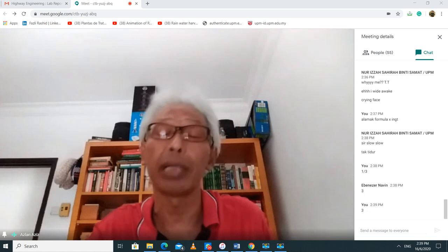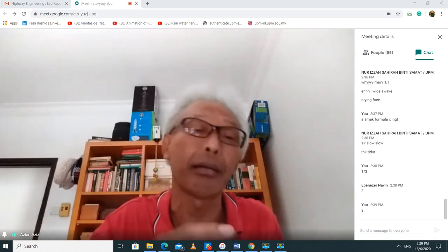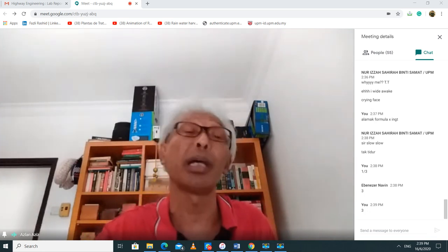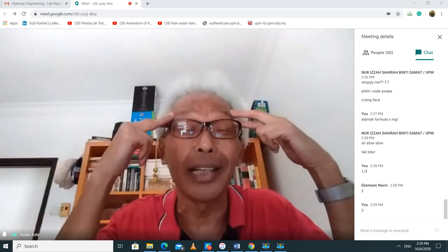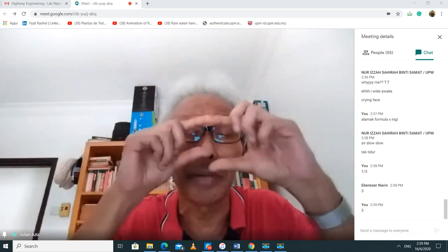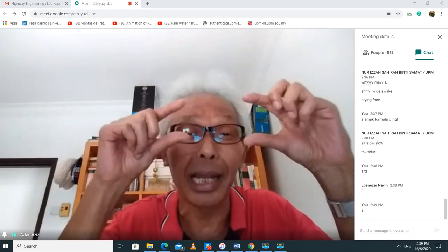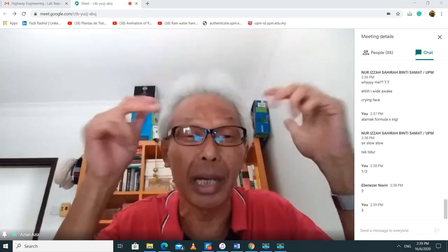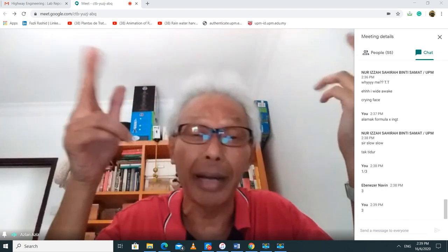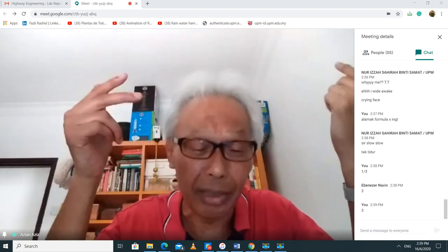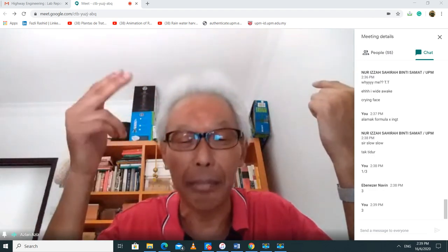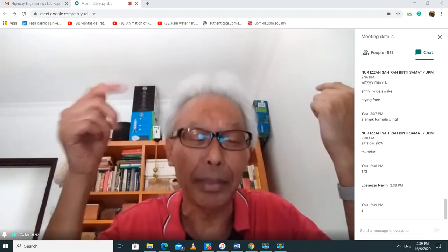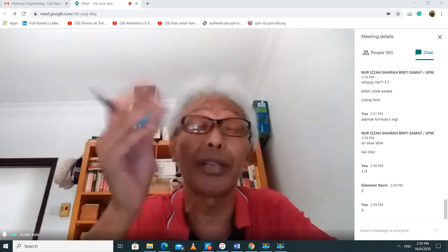Now, why am I talking about KP bigger than KA? I am trying to remind you that this KP is to do with the failure of soil. Again, I'm talking to you about an element of soil. You have sigma V and sigma H, and this KP is related to that sigma V and sigma H. You multiply KP by gamma and Z, the stresses, and it will give you failure.